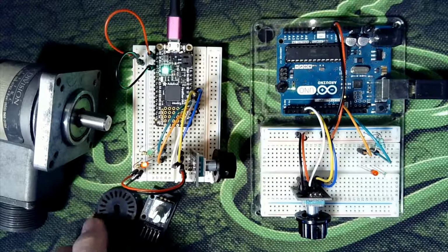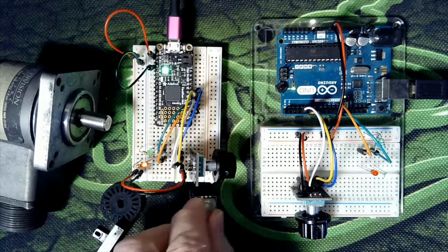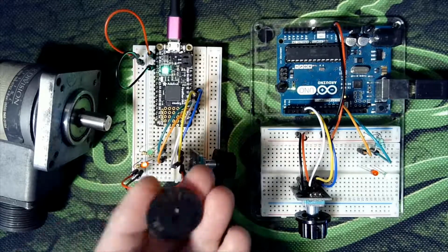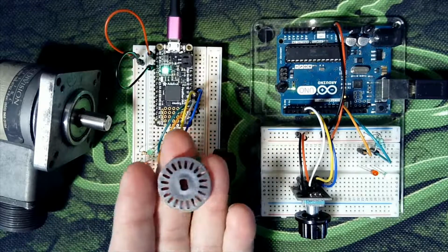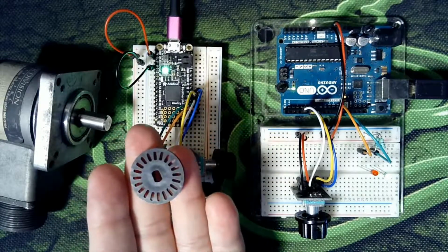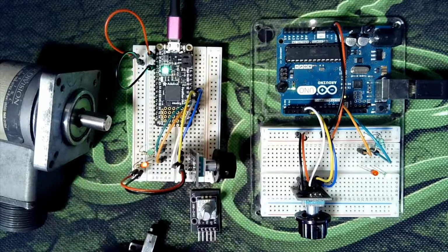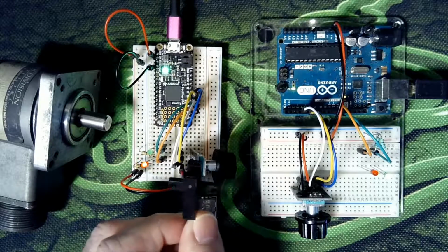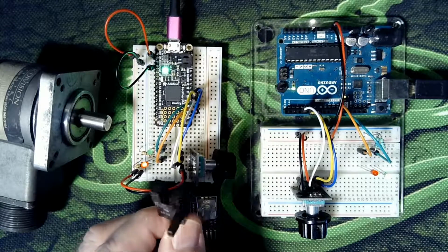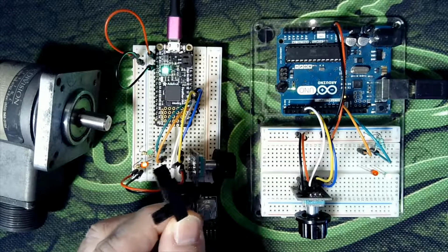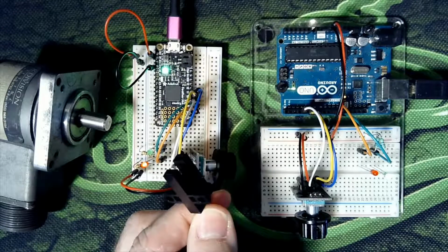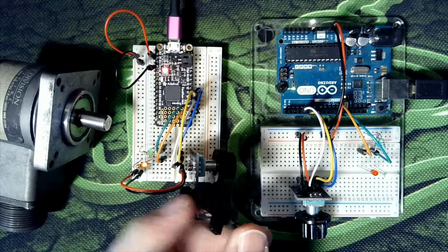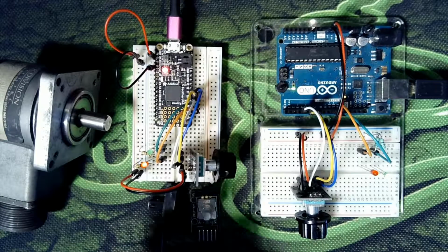The next one I have up here is more of a commercial one, and it's a little bit heavier duty, still used a lot in the hobby industry. What I have here is an encoder wheel, and as you can see, there are all kinds of slots in it. The slots allow light to come through. And then you use something like this. This is an infrared emitter and detector in a package. Now you could use it without the package. The advantage with this is it is very precision made, with a very slight slit in the plastic to allow the light to come across. So it's a very narrow beam of light.